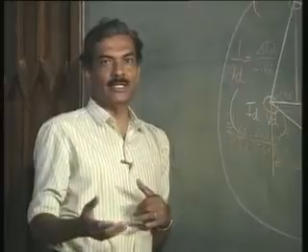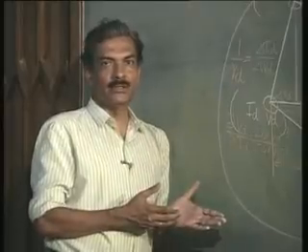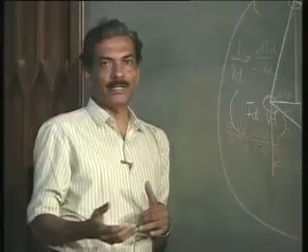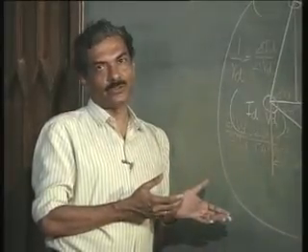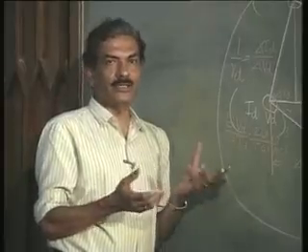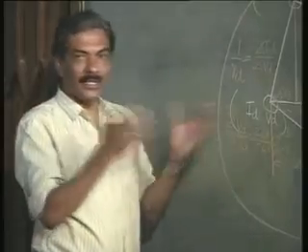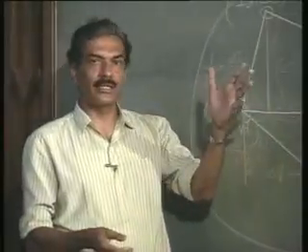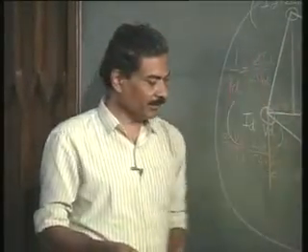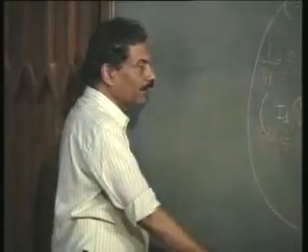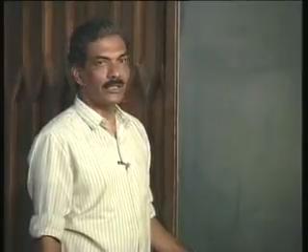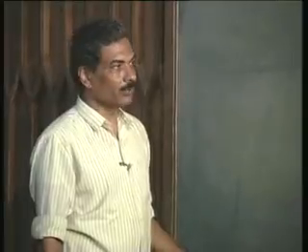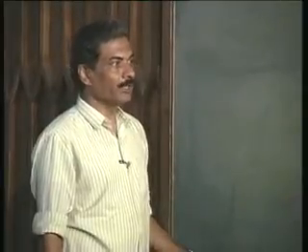If it is operating at 2 milliamperes, it is 13 ohms. If it is operating at 4 milliamperes, it is 6.5 ohms. So, you can easily evaluate the small signal resistance without really knowing anything about the diode characteristic at all. So, this is a very useful information regarding the diode and its small signal property. This can be usefully utilized later when we use the diode in its forward bias mode and fix the operating point.